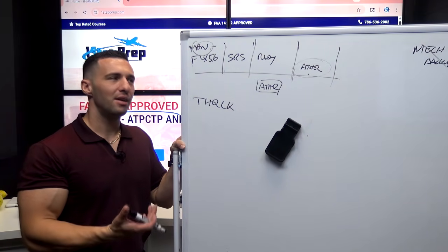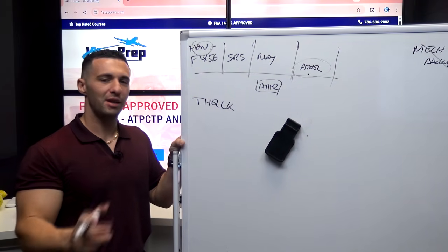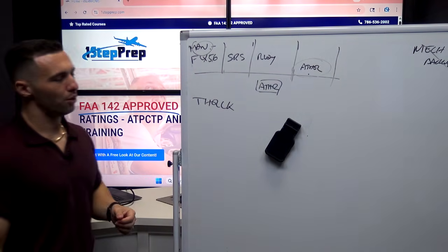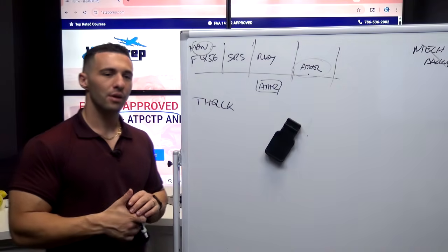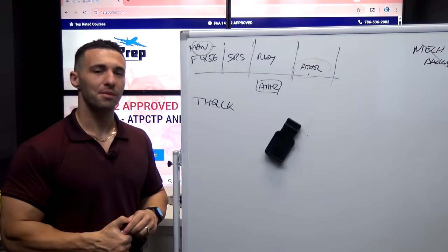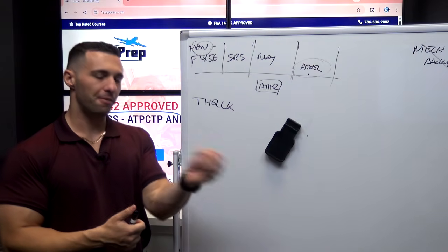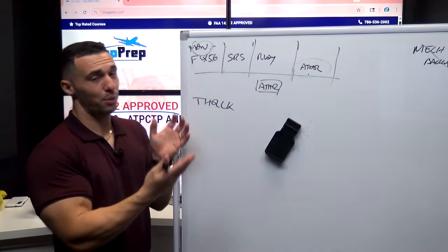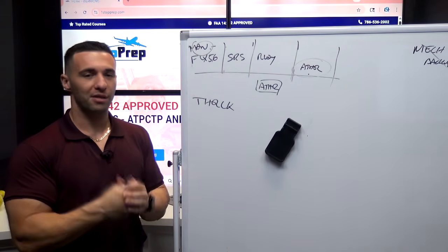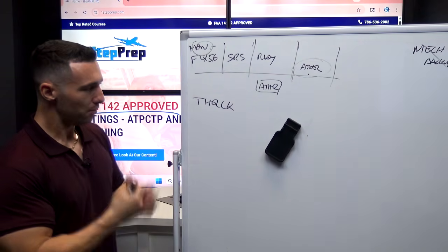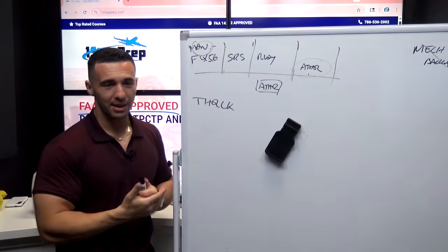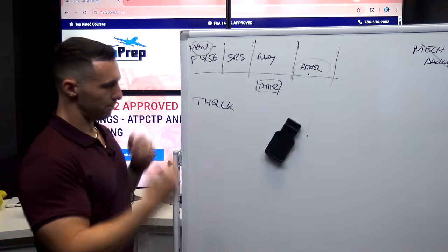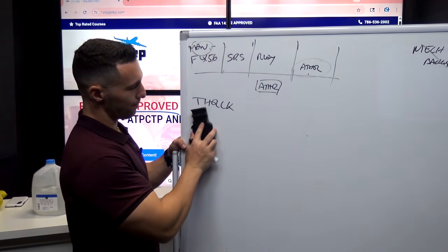Because you have to understand, if you deselect auto thrust on the FCU, the auto thrust system interprets that as an auto thrust channel failure, an auto thrust system failure. And anytime the auto thrust system fails, it defaults into locking the last sensed thrust value. So that's why we get thrust lock as an ECAM that pops up and says you have this condition. Now, ultimately to get out of here, it's really no big deal. You just move the thrust levers and you can go back and restore your auto thrust.